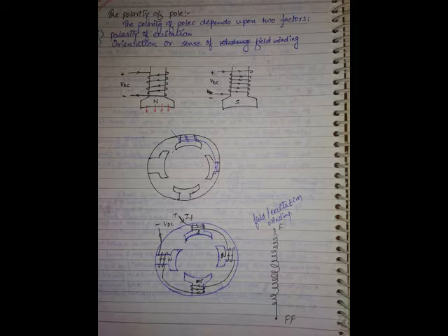So the idea of lamination is, instead of going for a solid cylindrical drum like that, you go for thin sheets like this. Let us say this solid drum is cut into 10 or 20 pieces, each having 1 mm thickness.